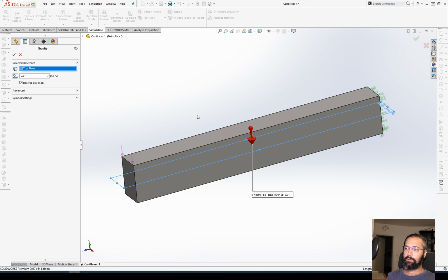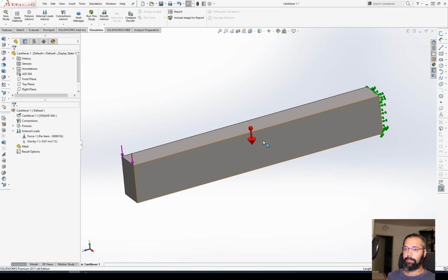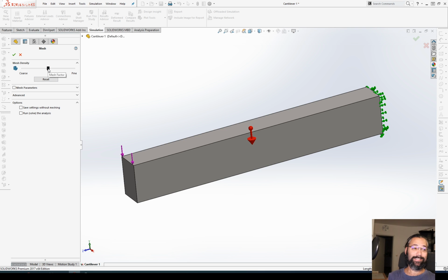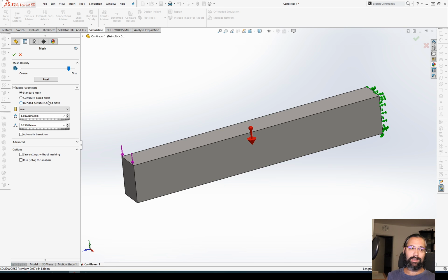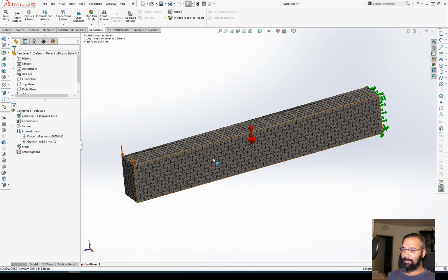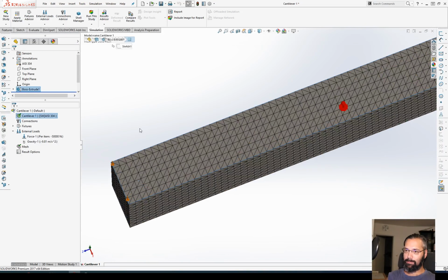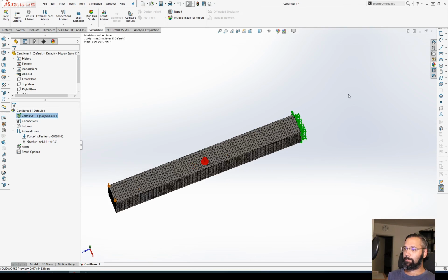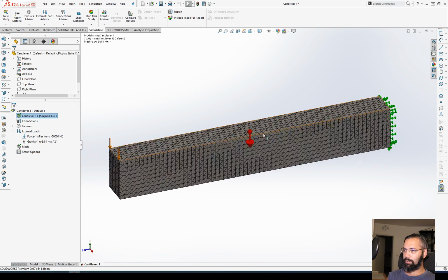So we're going to do gravity, which is 9.81 in the direction of down, and we're going to mesh here. You can do courses upon courses about meshing, but this tool is not very refined. But for this size, for this length of 400, you have about 40 elements along the longitudinal line. That's fine. For this, it's all right.